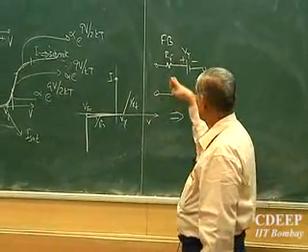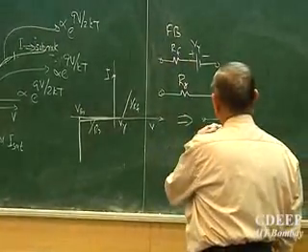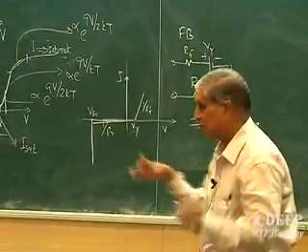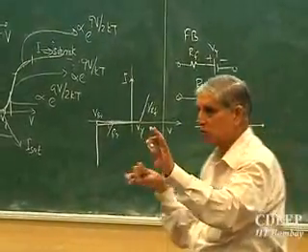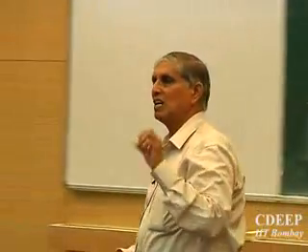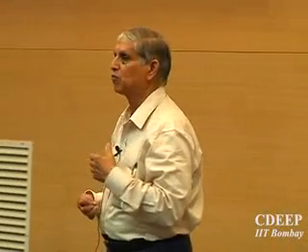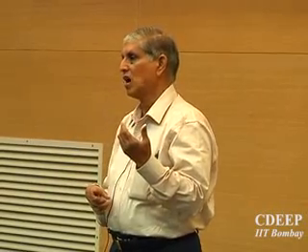Different tricks are used to make that. So essentially, what I was expecting this to act like is a switch: RF 0 and RR infinite. When I open, RR is infinite; when I short, RF is 0. This is what an ideal switch is. So in the design of a diode or a PN junction, what are we trying to achieve? Low RF and high RR, because then I get an electrical equivalent of a switch. So design of a diode looks for small RF and large RR. Large breakdown too, because if I have 3000 volts to block, V breakdown should be larger than 3000, because then only it will block that voltage. Is that point clear?